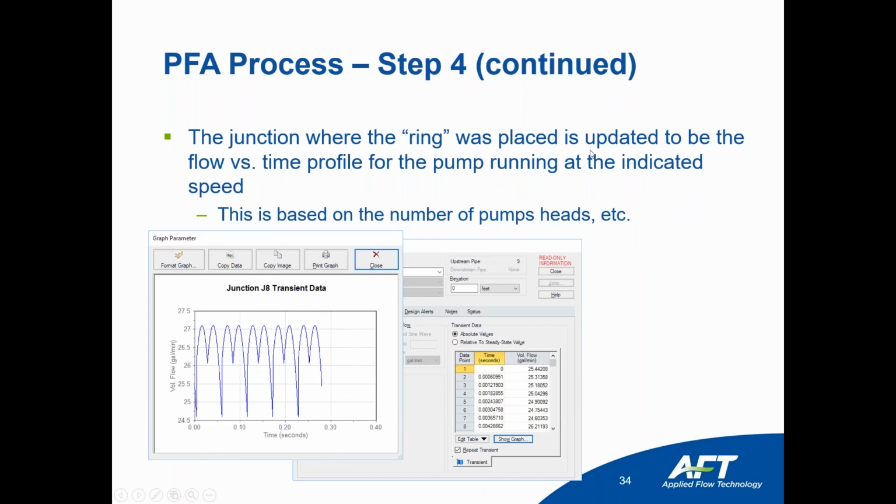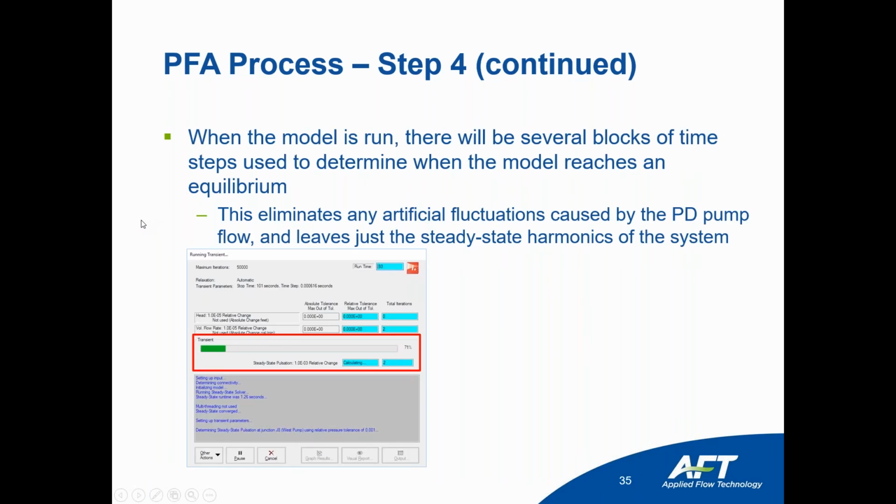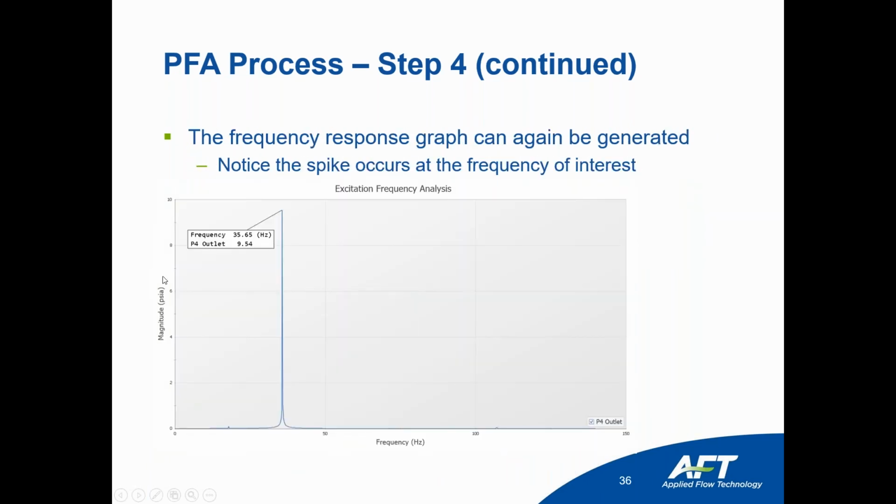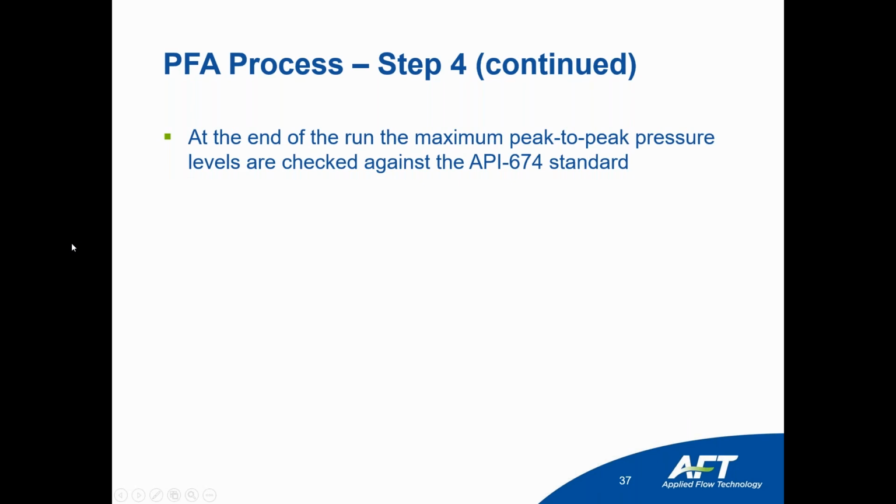So as I said, this would be step 4. The table we went through in the program showed the pump's RPM, so it created scenarios. Here are the scenarios created automatically for you to check the RPM if we operate the system at those pump RPMs. They are read-only, so most of the model cannot be changed. They will be deleted when the parent is changed. So when you change the parent, you make any change, you have to go through the process again and check the system.